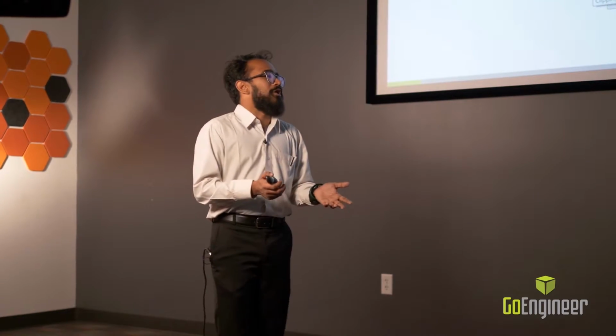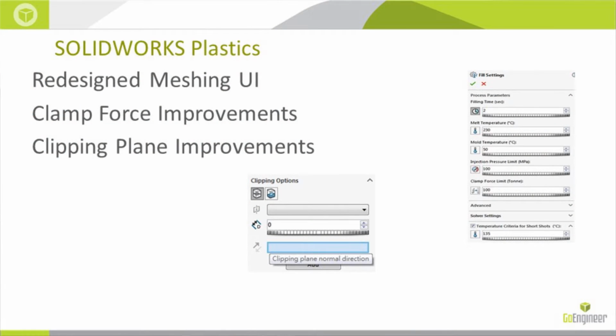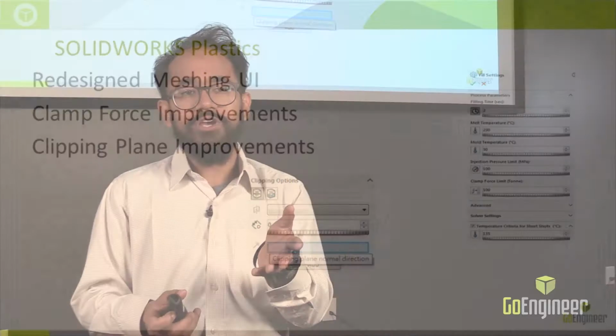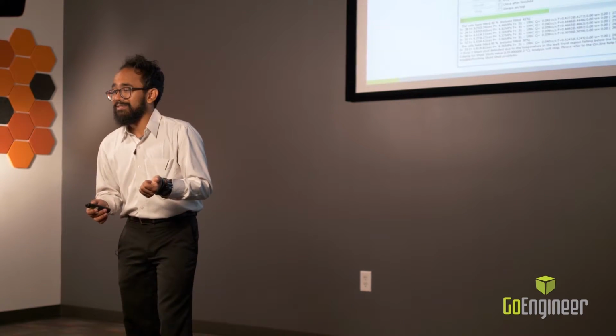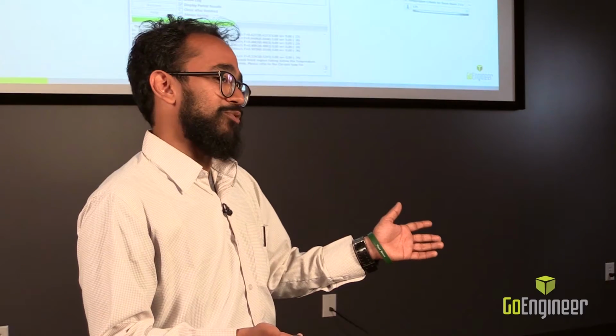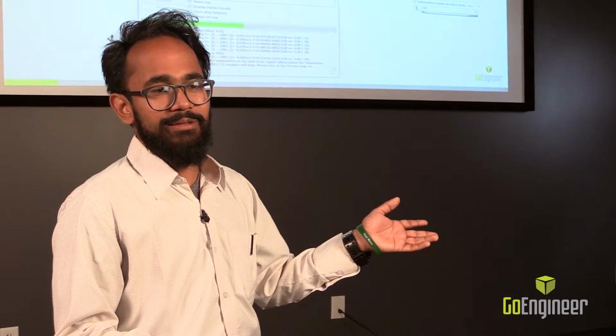Next line of enhancements involve clipping plane improvements. Typically, you were restricted to only 3 default clipping planes, but now you can use reference geometry from SolidWorks in order to create different clipping planes that then allow you to look at results within your geometry without having to deal with the UI.